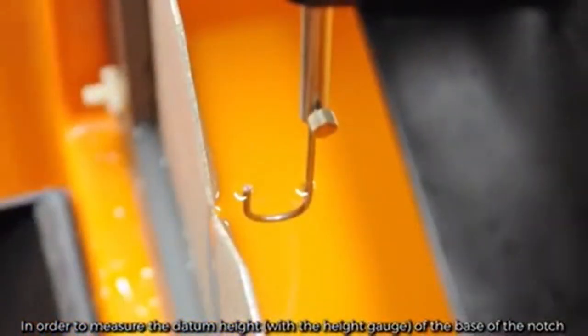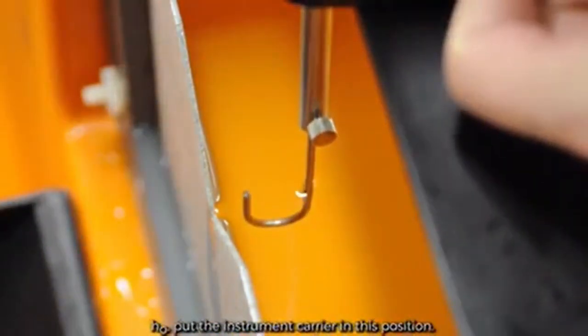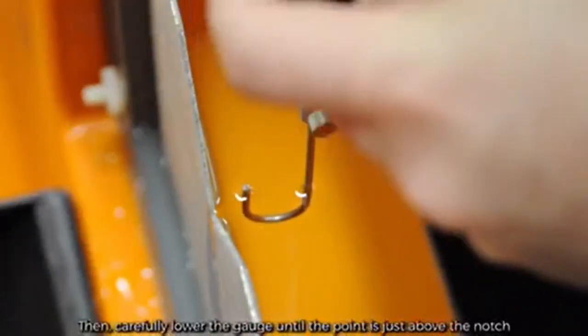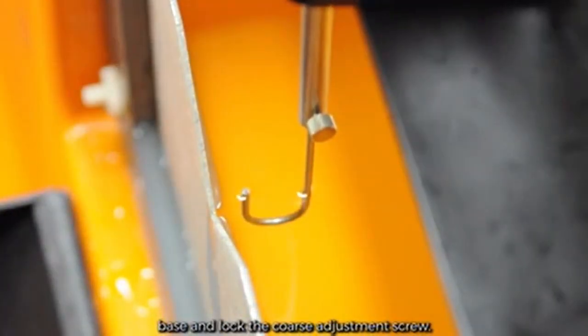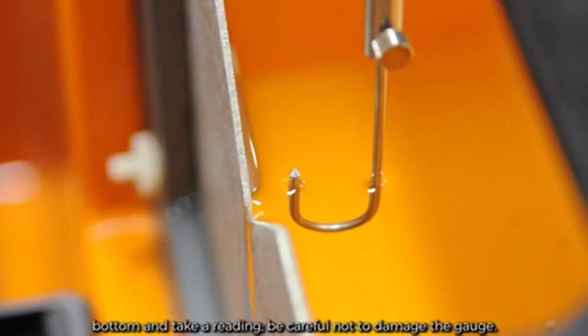In order to measure the datum height with the height gauge of the base of the notch, H0, put the instrument carrier in this position. Then carefully lower the gauge until the point is just above the notch base and lock the coarse adjustment screw. Then, using the fine adjustment, adjust the gauge until the point just touches the notch bottom and take a reading. Be careful not to damage the gauge.